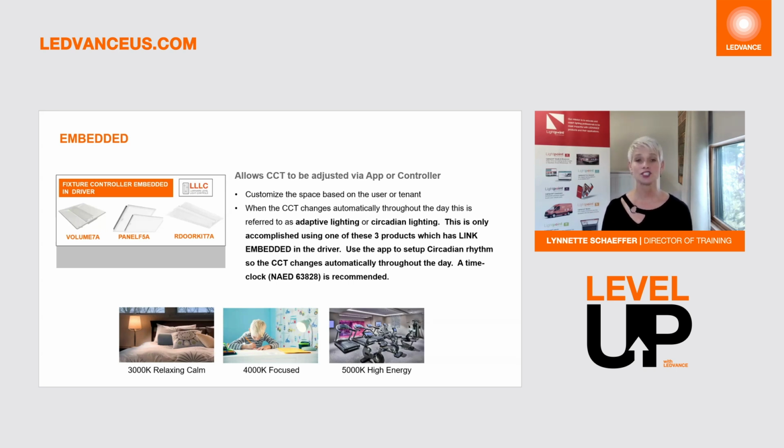But what's cool about being able to change the CCT is it does truly allow for the space to have customization based on the user, the tenant. And again, you can easily change it via an app or the wireless controller using the scene function. Now, I do want to add, there is another really cool feature. If you want the CCT to change automatically throughout the day, the industry refers to this as adaptive lighting or circadian lighting. You can use the app to enable circadian rhythm so the CCT changes automatically throughout the day.